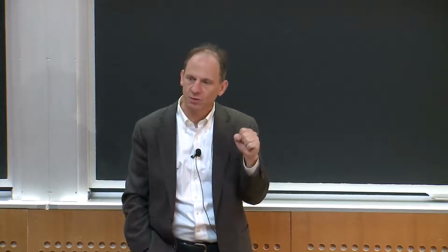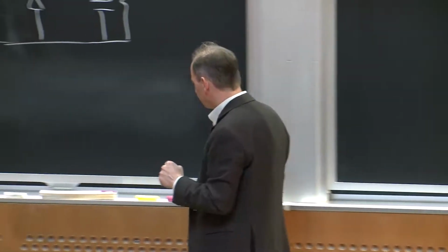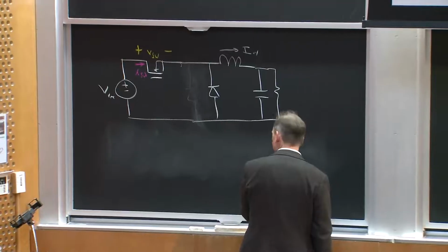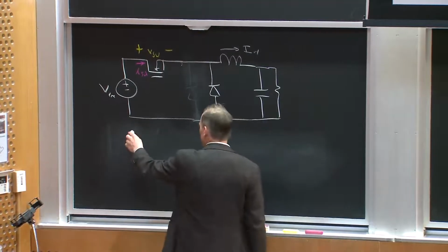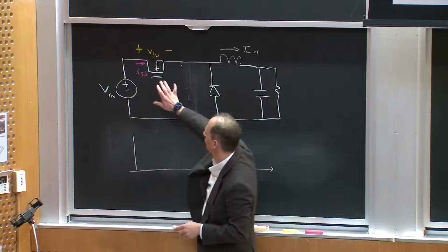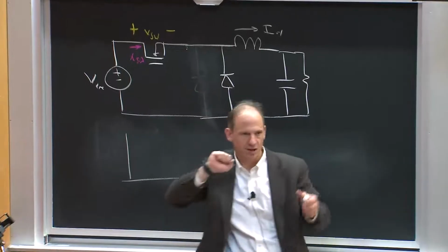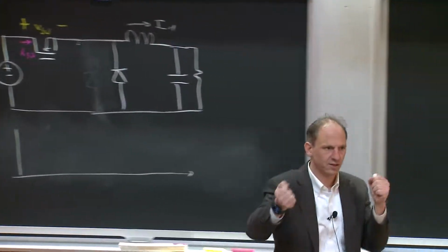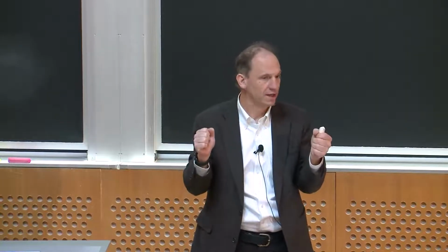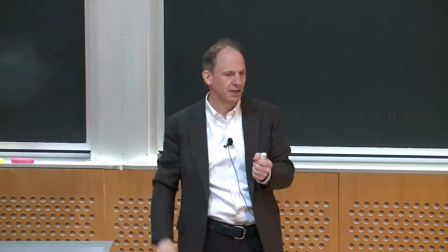We also said you have to worry about switching losses in the device, and we might approximate switching loss this way. Let me just focus in on the tiny part of the time cycle when I'm turning this device on and off, switching between the two devices. In an ideal world, that happens instantly, but in the real world, it doesn't. Depending upon my switching frequency, it can take maybe 1% of the cycle or something like that.